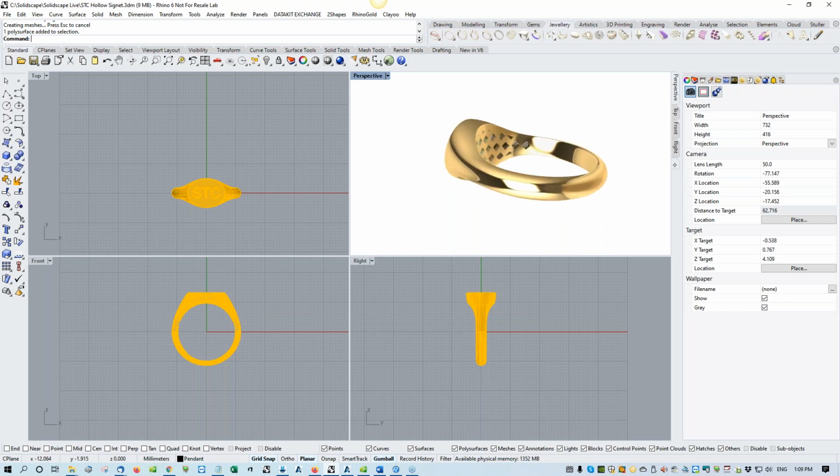Now, this model is a mathematically defined model, which has mathematically defined shapes. It's very smooth, and it represents exactly the shape that we want to print. However, the 3D printers will not accept the mathematical description of the model. They need a much simpler definition of this model, which consists mostly of just points on this surface. So what we need to do is convert this model into a mesh, which can then be sent as a so-called STL file, which stands for stereolithography.